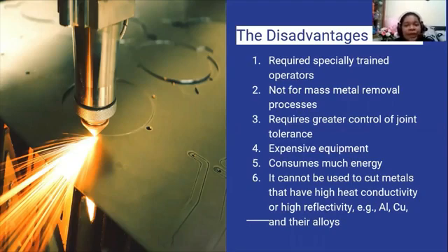Even though laser beam machining has advantages, it also has disadvantages or limitations. The first one is that it requires specially trained operators for operating the laser beam machines. The second, it is not for mass metal removal processes. The third, it requires greater control of joint tolerance. The fourth, the equipment is a little bit expensive and it consumes much energy.